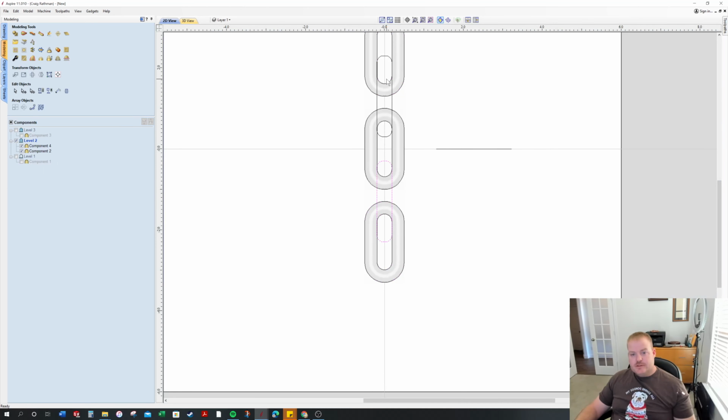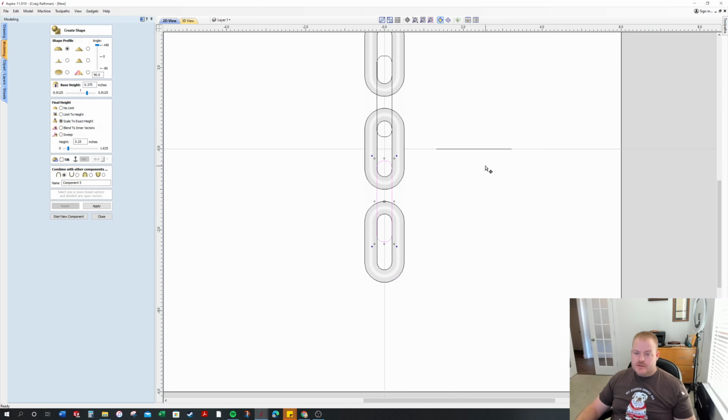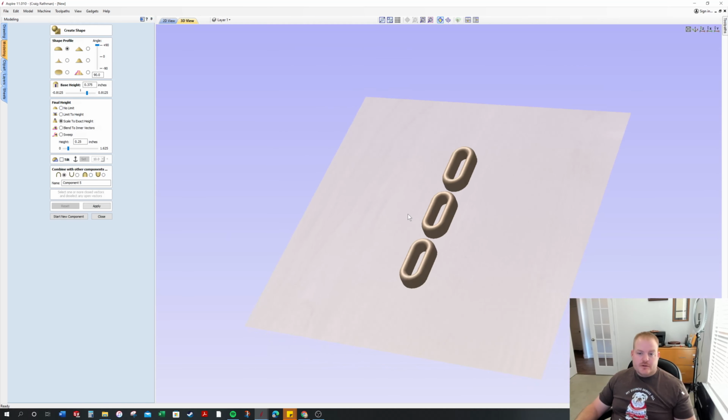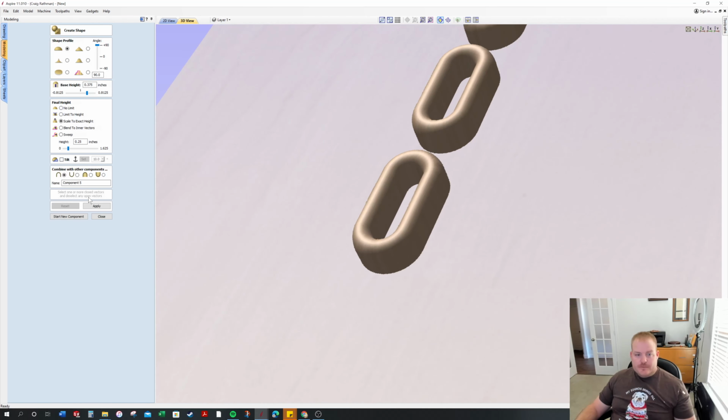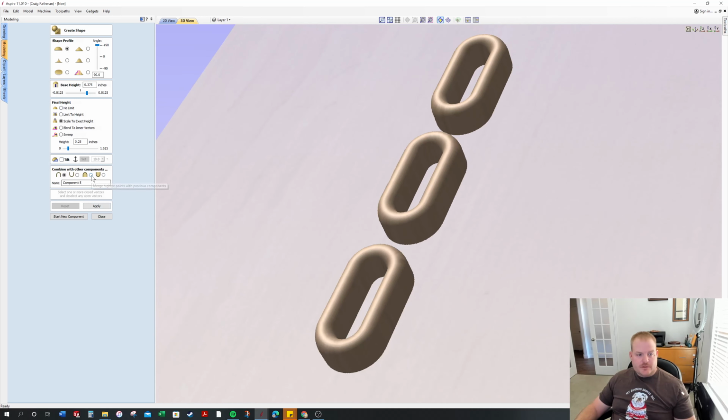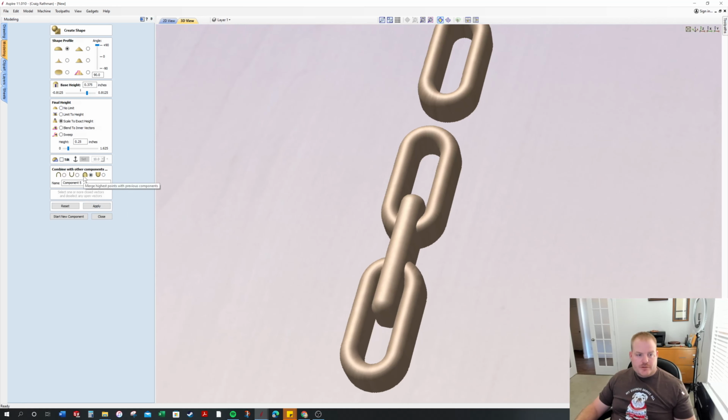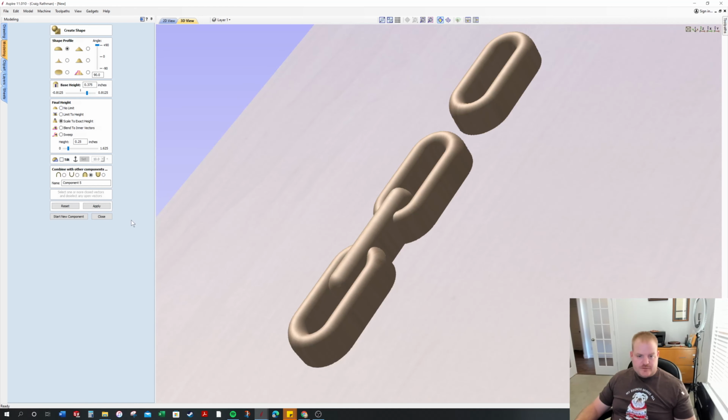So then you come back to these 2, and I'm going to create these separately because they're going to get moved around a little bit, and if you create them at the same time, it's one component and you can't modify it like I'd want. So the one thing you want to notice is you want your base height a little bit taller, which I did 1/8 of an inch taller, so it protrudes past these first links. And you don't want it on that, because if you do, it does that goofy stuff. So you put it on merge. So that's the first one.